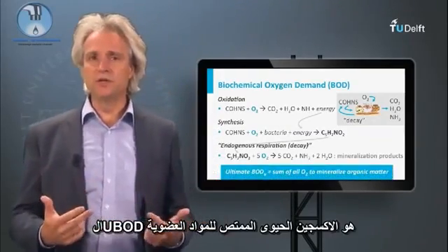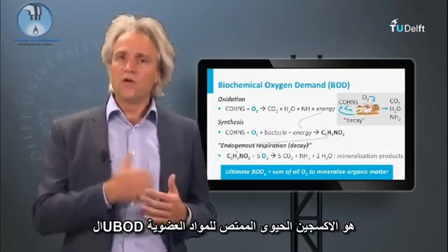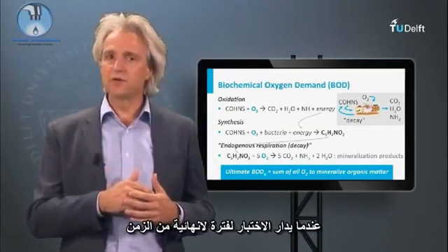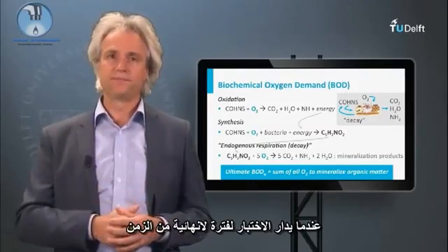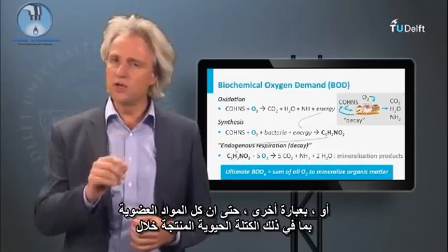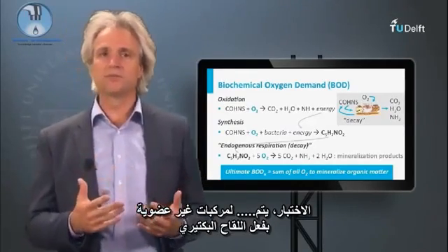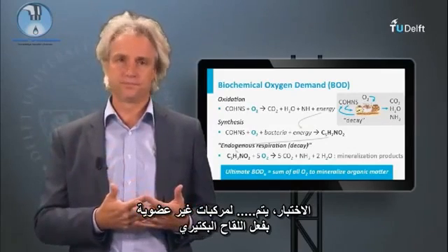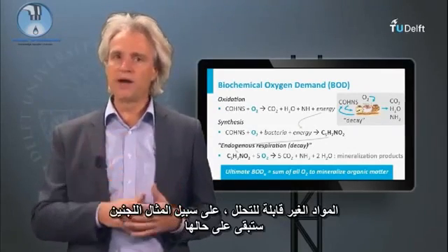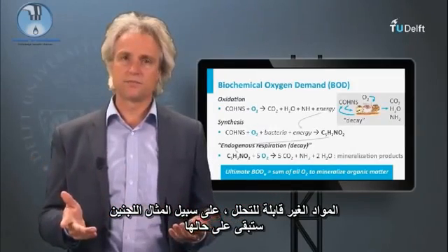The ultimate BOD, therefore, is the biochemical oxygen demand of the organic substrate when the test is followed until infinite periods of time. Or in other words, until all organic matter, including the biomass produced during the test, is mineralized to inorganic compounds by the bacterial inoculum. Non-biodegradable matter, for instance lignin, will remain untouched.